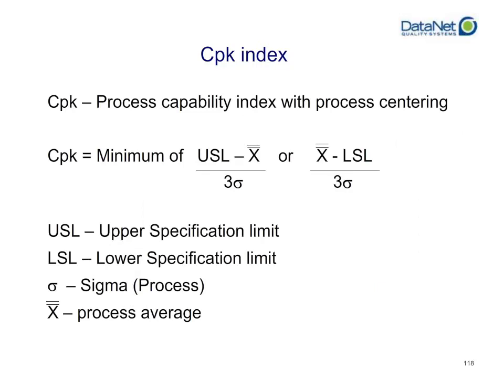If we want to determine the capability of our process, we need to introduce another metric that can tell us if we are not only capable of producing within plus or minus 3 standard deviations, but if we are targeted, meaning if we are centered at wherever we want our ideal output to be. CPK is the process capability index with process centering.